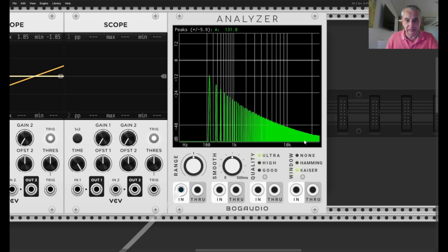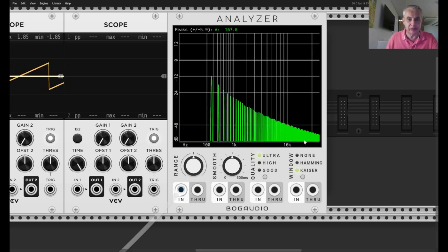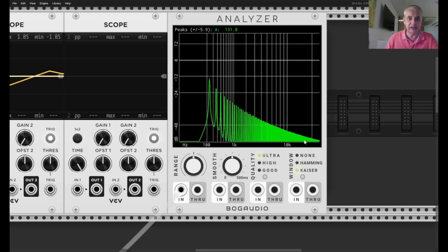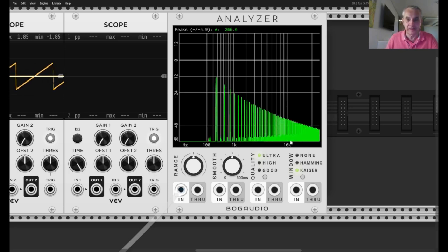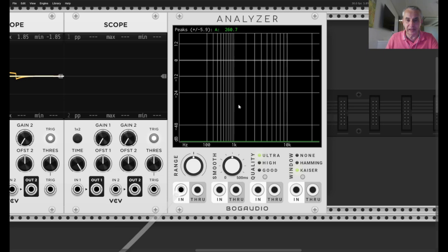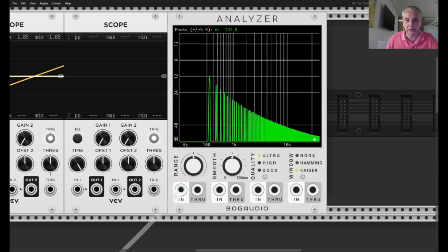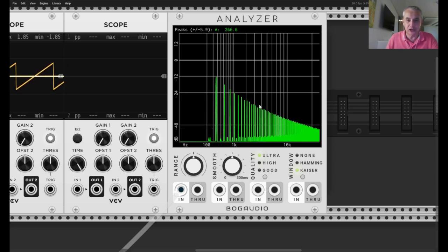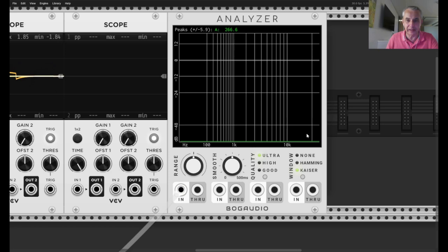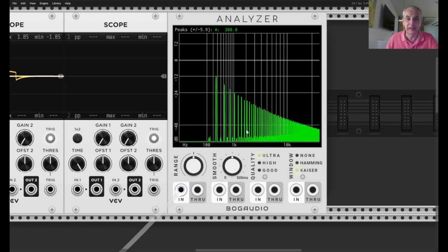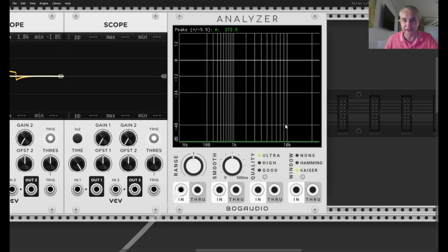And you can really hear it a little bit, but you have to have good ears, and maybe on YouTube it's not really audible, but you can definitely see it in the graph. Instead of having a nice curve going down, which you seem to have in this lower frequency, if I go one octave higher, it looks like the ramp stops here and then goes down back to frequencies lower in the spectrum. Those are actually aliases.